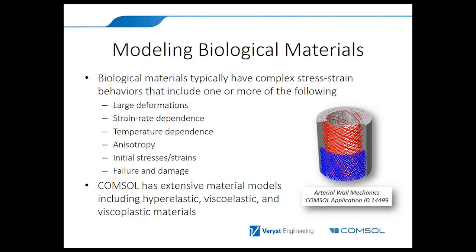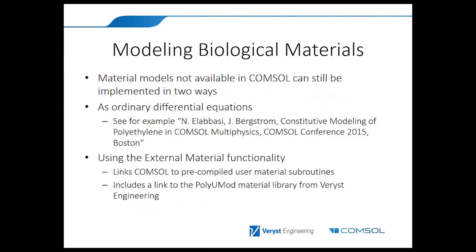But chances are you're going to run across a material model that is not implemented in COMSOL or any other code that you use. There are 2 options for dealing with that in COMSOL. The first is to implement your own ordinary differential equations that capture the behavior of that material. Not trivial, but doable for certain. There's a paper I presented at the COMSOL conference last year that shows how to do that for polyethylene.